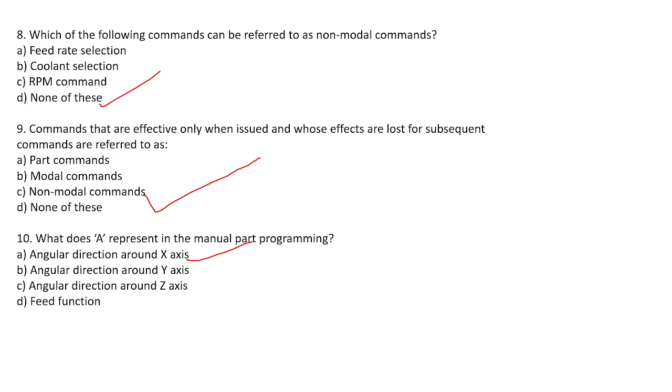There is one more way of programming actually. Instead of IJK, some machines use R straight away. Those IJK commands were initially primitive coding, and later they were modified according to evolution.